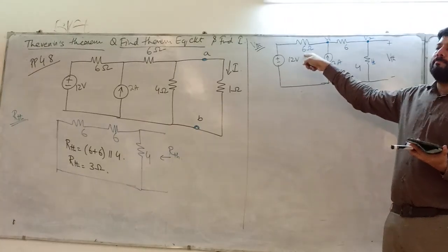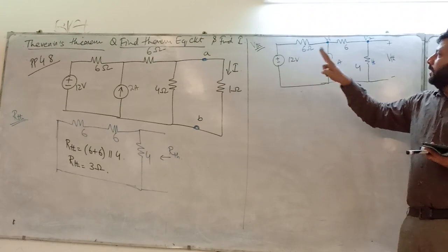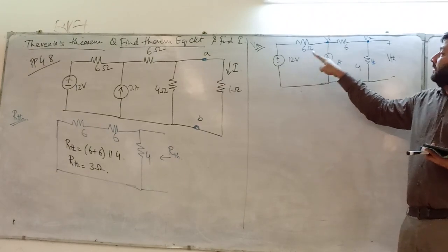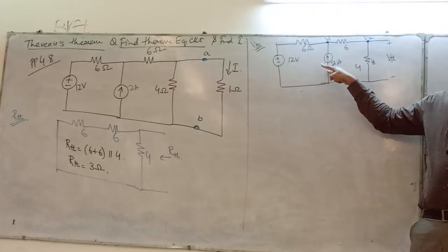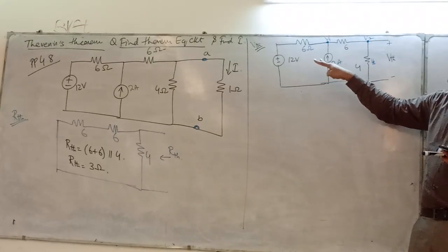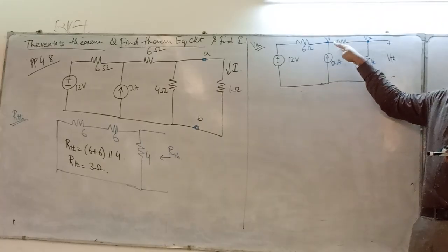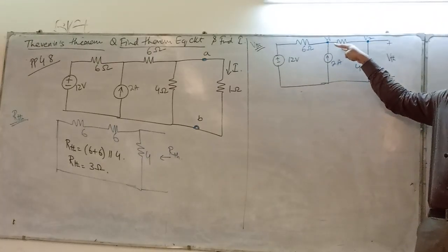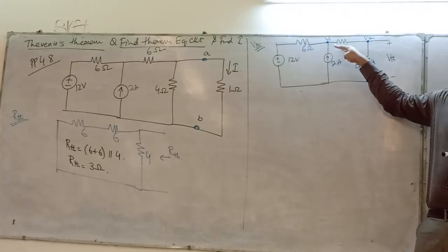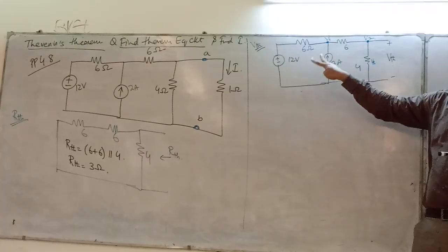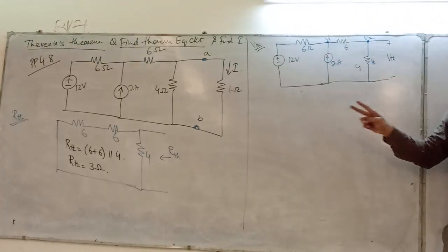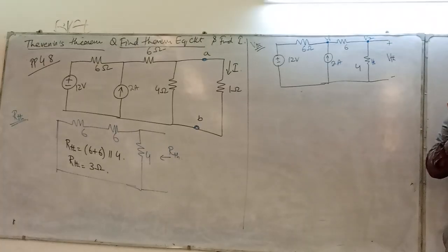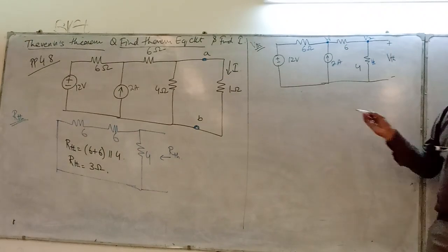Current source will be 2 ampere and a parallel resistor, and then 2 parallel current source, they will be added, and then this resistor and this, they will be in series. No. We will convert that current source into a voltage source, and then we will have a VDR circuit. So this is also one way. But what is the easiest way? Nodal.